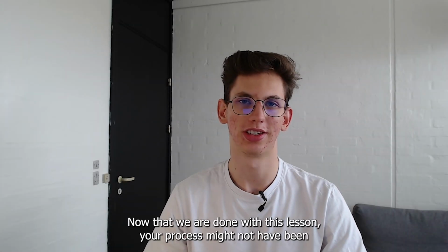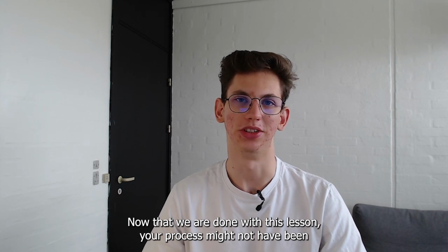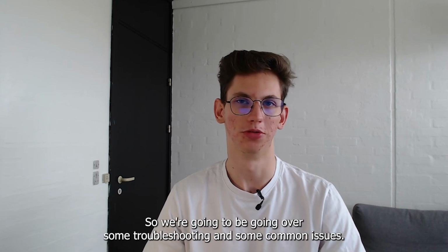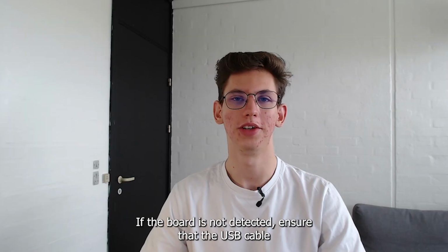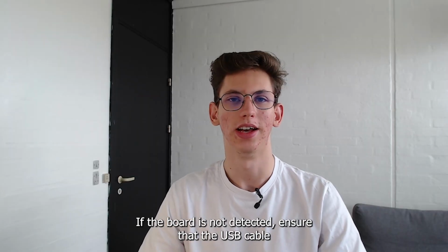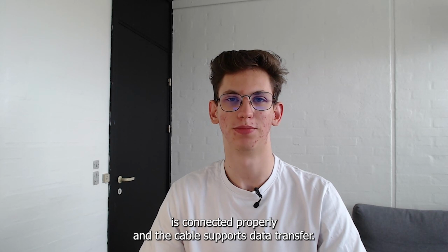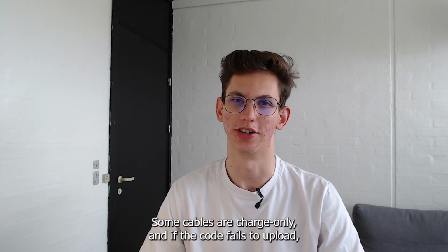Now that we are done with this lesson, your process might not have been so streamlined as mine. So we're going to be going over some troubleshooting and some common issues. If the board is not detected, ensure that the USB cable is connected properly and the cable supports data transfer. Some cables are charge only.